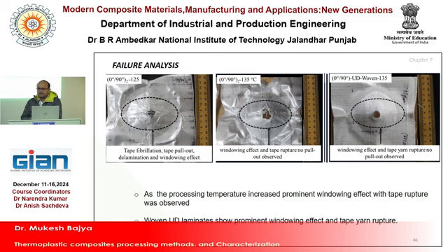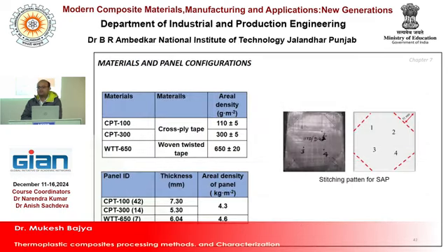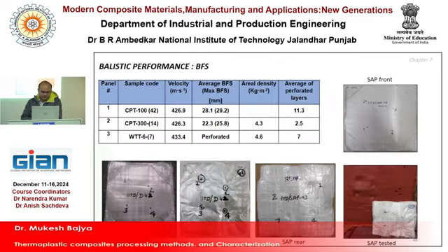These are the failure analyses after the tensile as well as the impact tests. This is the low velocity impact, and then we prepared the soft armor panels, and we tested these soft armor panels against a 9 mm bullet, and we successfully obtained impact resistance properties from these materials, equivalent to the imported item supplied by DSM Dyneema and Spectra. And here you can see the impression. This impression is very small after the bullet impact. This is the real time bullet testing.